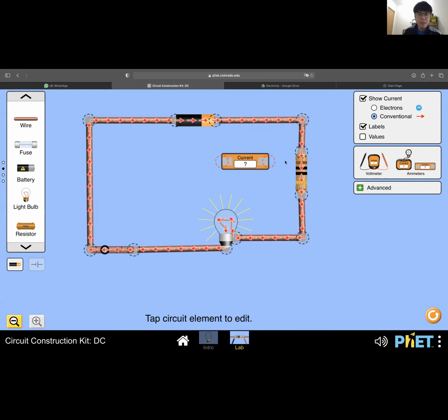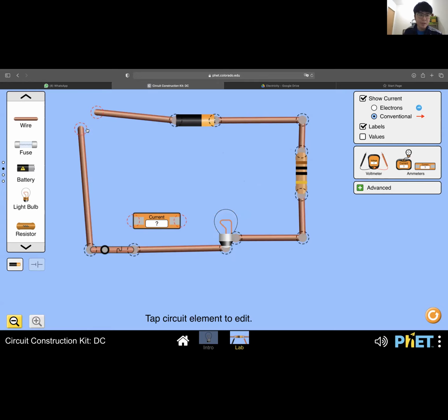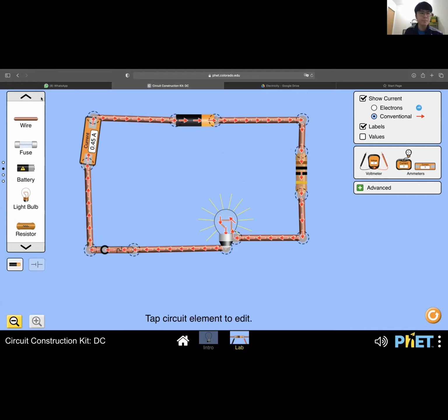Okay, you can see the load here. They are all connected one after another. Same for the ammeter. The way I connect the ammeter is also one after another. So, series. In other words, I connect them in series. Let's say I'm going to add this over here, this one here, and then this one connected here.